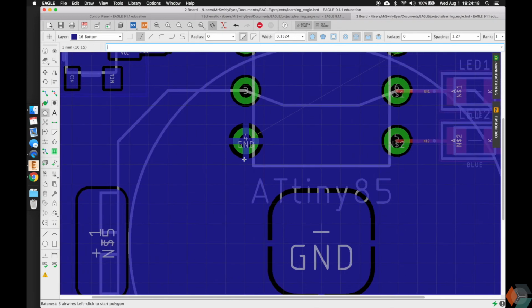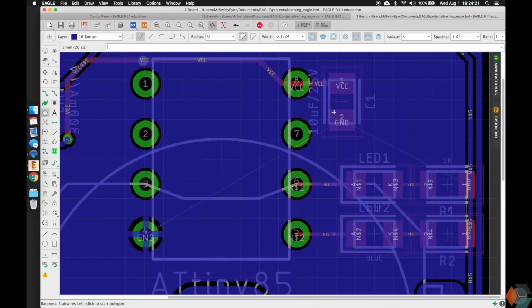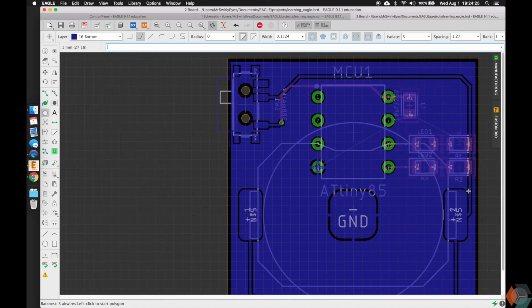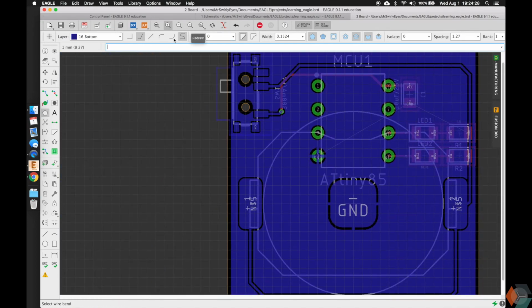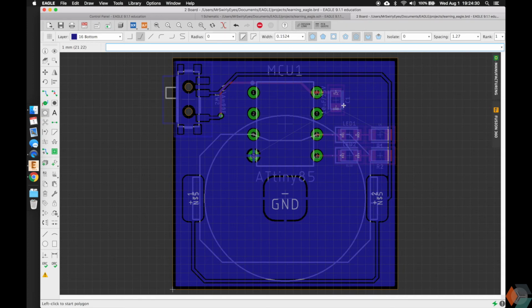So for the pad, you'll notice that the ground is connected, and here on the top, you'll notice the ground's not connected yet. So we need to still make those connections. So what I was trying to say earlier is when you type in ratsnest, it'll shorten all the air wires to their shortest connection if we move components, and it'll also fill in the ground pours.